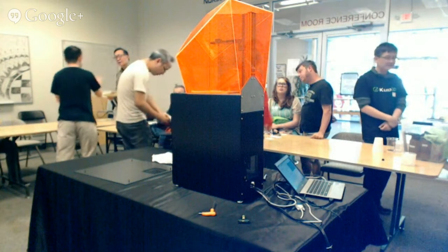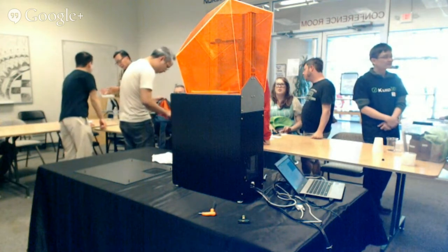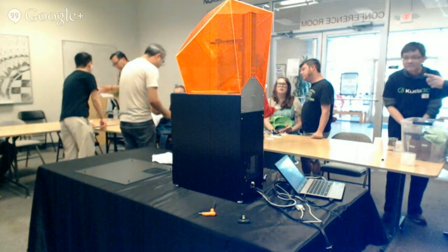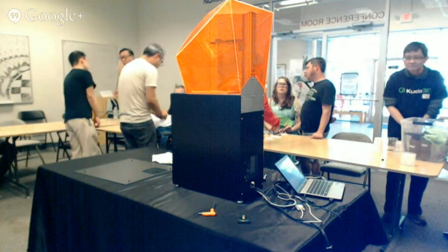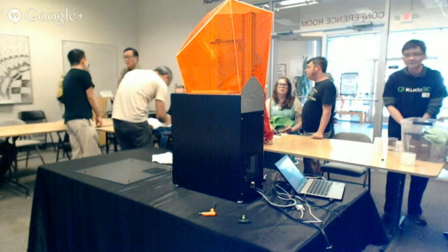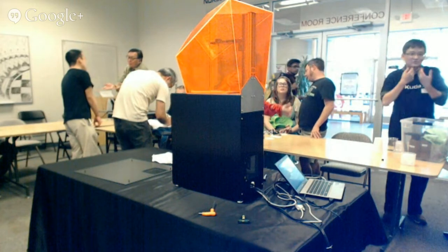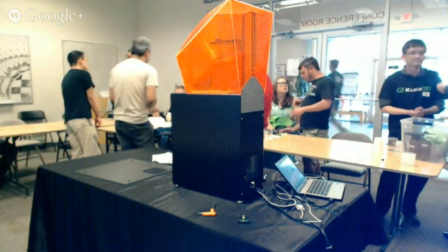This part isn't strong enough to go in the injection molding machine. I had another version of this, and I took it back to the Morgan press to inject it, and I did something a little wrong. The press came down and blew the mold apart. And that's partly because between this dip here and the bottom here, you can see through it, right? There's not enough material there. So the Morgan press is 10 tons.